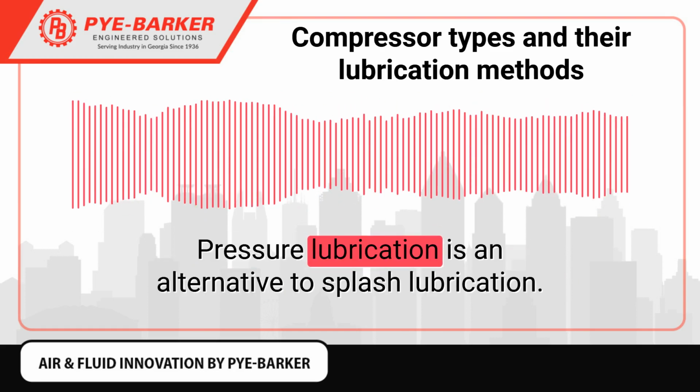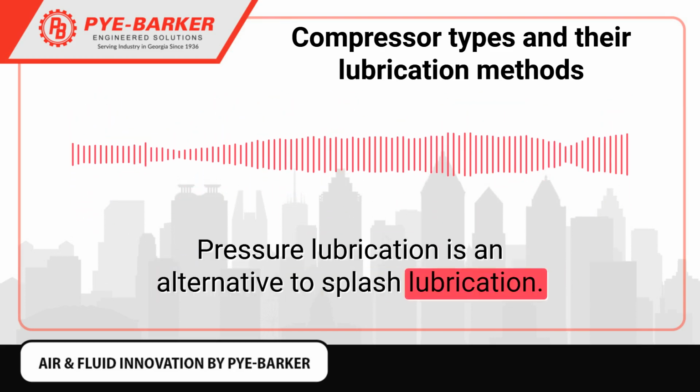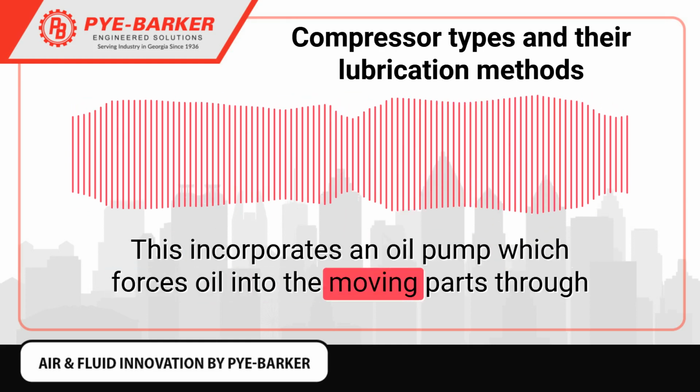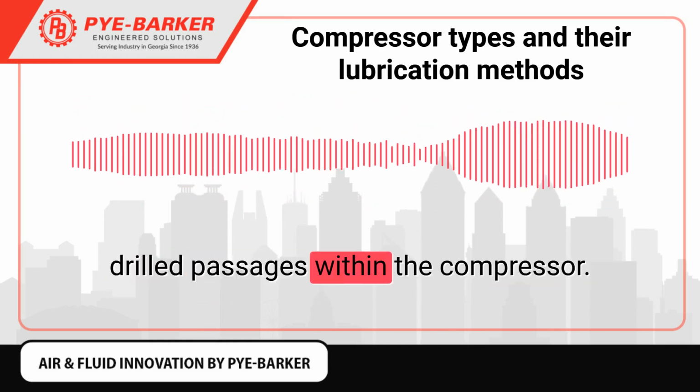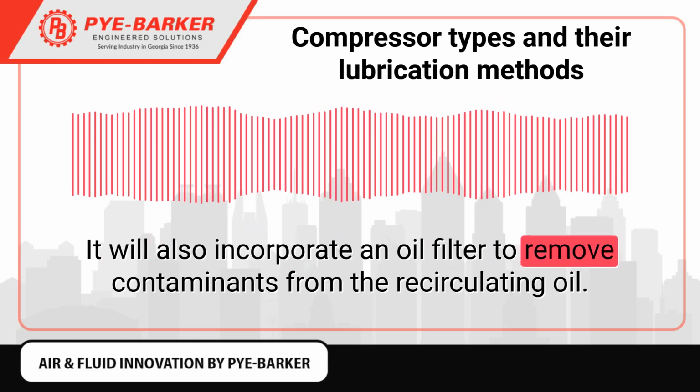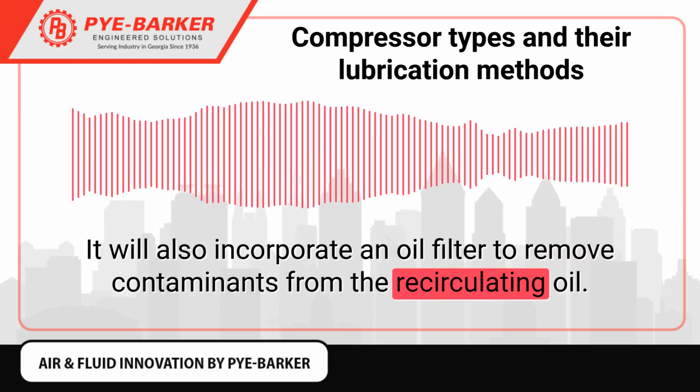Pressure lubrication is an alternative to splash lubrication. This incorporates an oil pump which forces oil into the moving parts through drilled passages within the compressor. It will also incorporate an oil filter to remove contaminants from the recirculating oil.